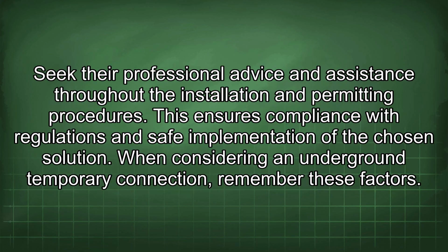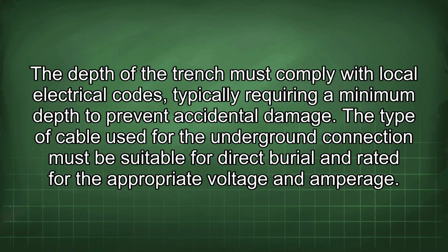Seek their professional advice and assistance throughout the installation and permitting procedures. This ensures compliance with the regulations and safe implementation of the chosen solution. When considering an underground temporary connection, remember these factors. The depth of the trench must comply with local electrical codes, typically requiring a minimum depth to prevent accidental damage.